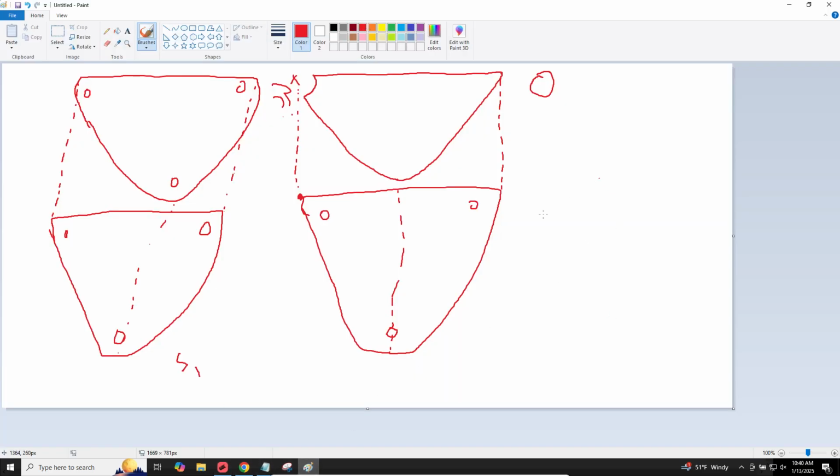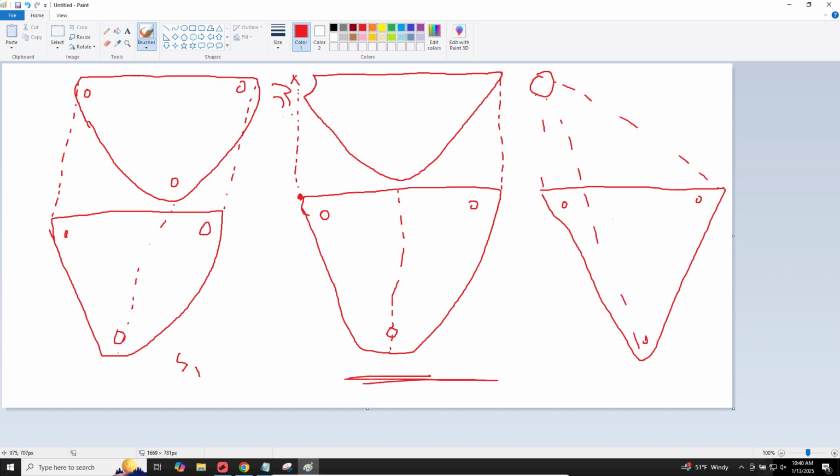If I go back here and draw another scenario, the hex mesher doesn't have enough information regarding, okay, do you want me to extrude this face to this circular section, which obviously doesn't make sense? Or do you want this scenario where it tries to extrude this first face S1 to the second face S2? You can see it's because these two sides, if you will, are no longer similar.